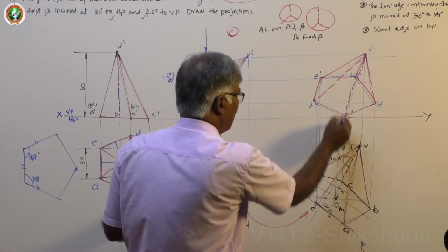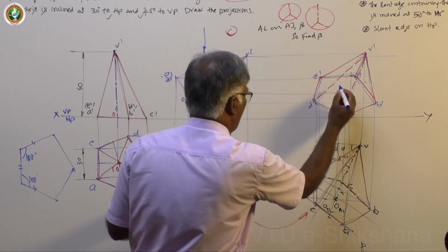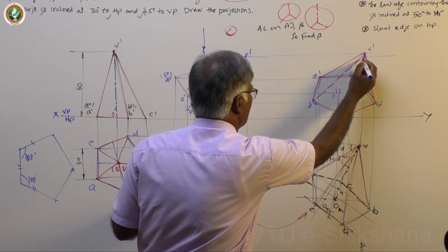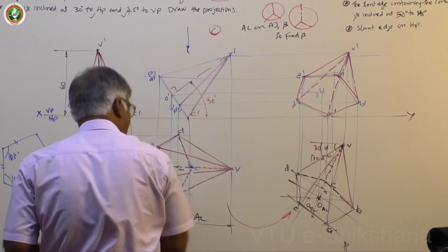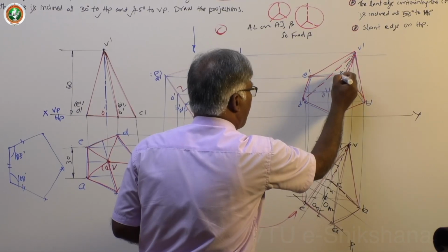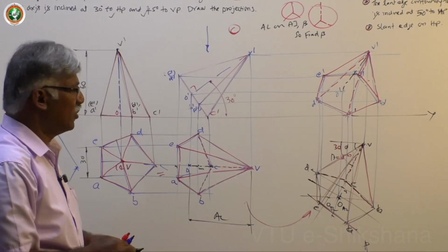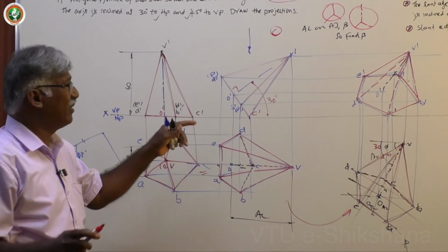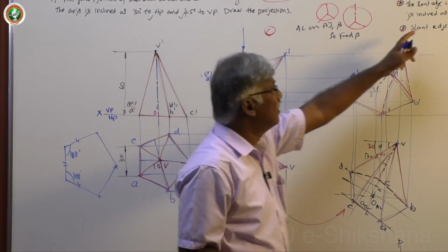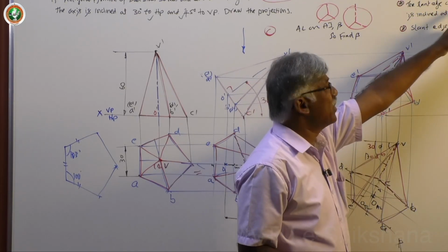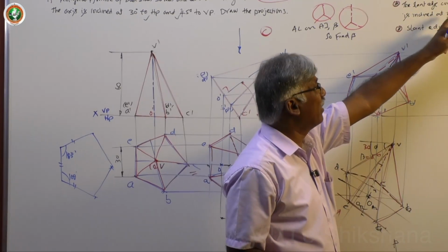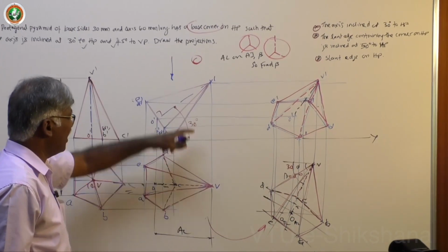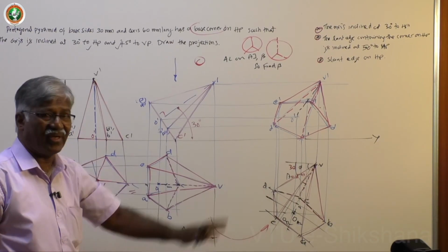Now add the axis also here. It is very important for all solids. Keep the axis represented. Suppose they ask the axis appears to be inclined at 30 degrees to XY, or again 45 degrees to XY, then you take it directly as beta, as I told you already.